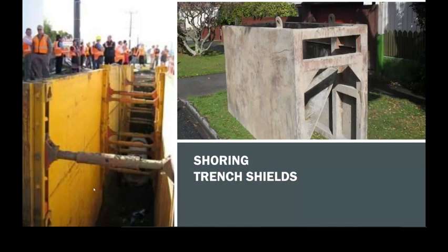With the timber shoring, unfortunately, you've got to dig the hole and then you've got to build it. So you're actually at a level of risk while you're constructing it, which is not as ideal. But these ones, you don't get in there until it's protecting you. And full shoring like this, if it's over-engineered, could also potentially allow other vehicles closer than that 45-degree zone of influence.